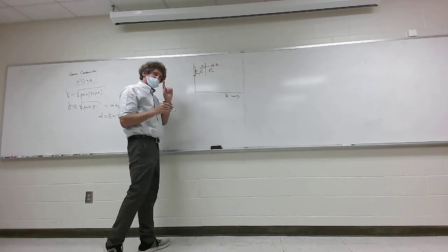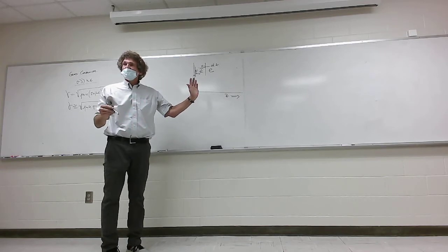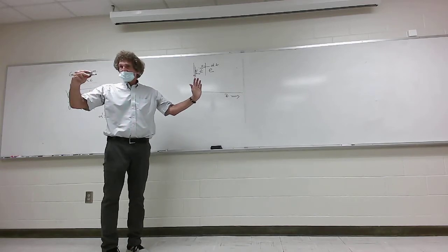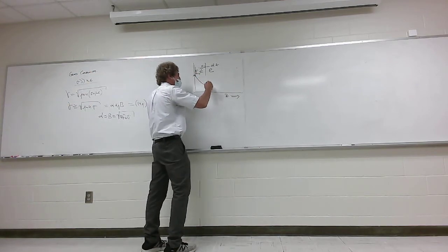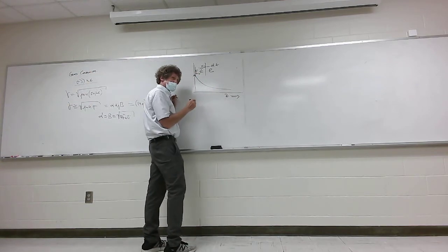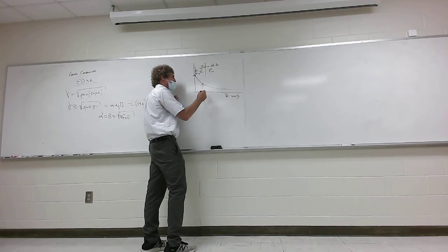Do y'all follow me? So what we usually do is plot the magnitude of that times e to the minus alpha z. Now this is where it becomes important. That alpha tells you that the further in you get, the smaller the magnitude of the electric field component. It's decaying exponentially. Y'all follow me? I just want to take a look at the maximum value of the envelope. So there comes a point right here